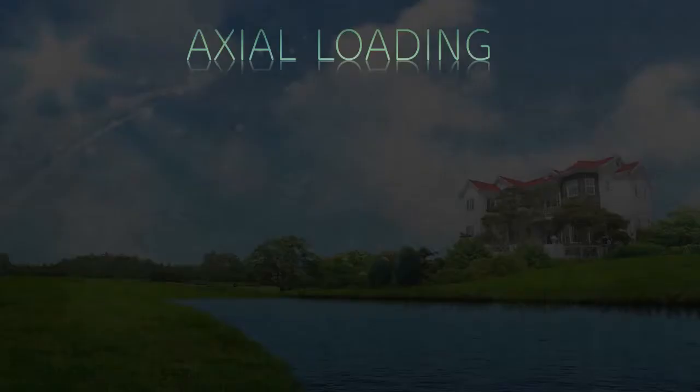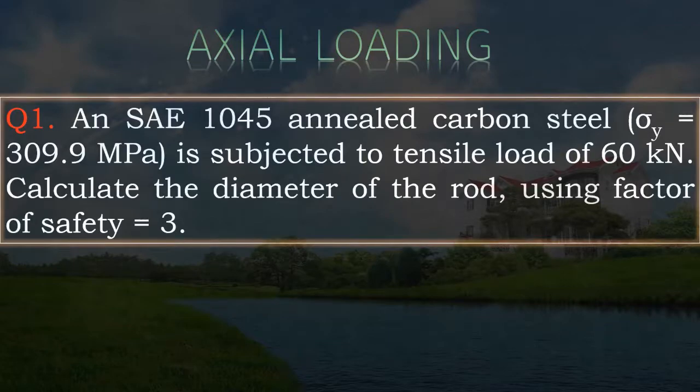Let us start the first numerical on axial loading. An SAE 1045 annealed carbon steel having a yield stress of 309.9 megapascals is subjected to a tensile load of 60 kilonewtons. We need to calculate the diameter of the rod using a factor of safety of 3.